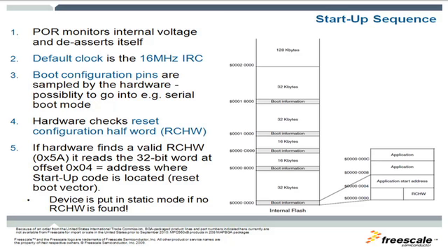will now look for some configuration information, and it looks in one of 5 locations. Usually we'll just use location 0 and forget about it. But if it's not there, it will look at the other locations. And the way it identifies the boot information is that there is a 5A written in a particular byte in this first word. So all our startup files will do that for you. You don't have to worry about it.